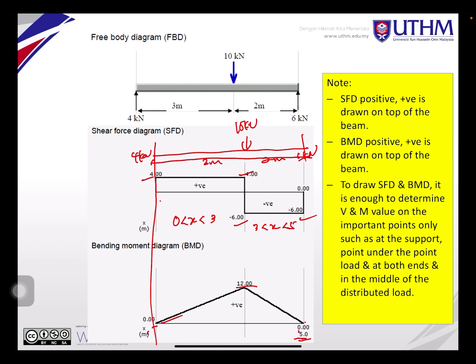So you plot graph shear force and bending moment, you get this graph. You should have kilonewton meter here, and this is kilonewton here for the unit. So this is basically how you draw by using the cut section. You cut at the section before the force and after the force, when you apply one load on it.